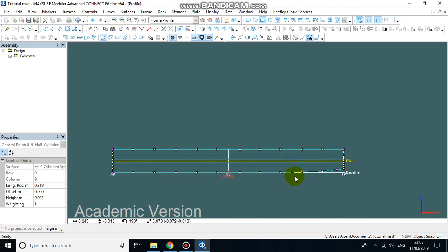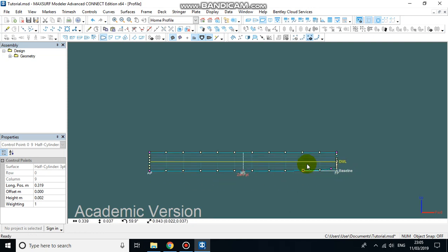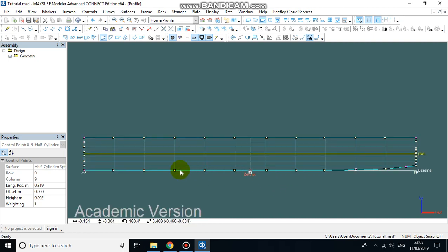A boat with big rocker, especially where the rocker falls roughly around the centre of flotation, will pivot quicker and react quicker. A very flat-bottomed hull like in this shape here will be a lot harder to turn, and actually it'll be a lot harder to get on the plane as well, because it'll act like a vacuum sucking the hull down.